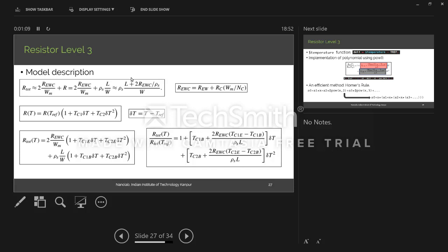Remember, all of this is just empirical modeling, no physics. In an actual physical model, the temperature would come in kT. If I had an actual diode model or an actual resistor model, I'd have it somewhere in the Fermi equation, in the Boltzmann equation. The T would be the T in kT. Everywhere you see a kT, you would see some temperature dependence, right? So all of this is just empirical. We're trying to model some sort of temperature dependence, and this is a good first fit. You can make a simple model out of this.